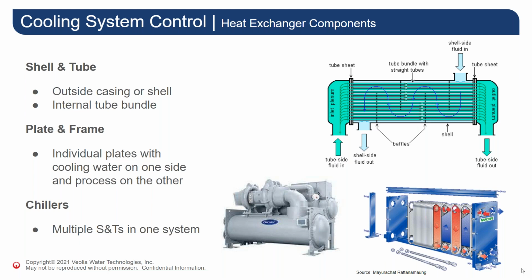Regardless of the type of heat exchanger, they all work similarly. A hotter process fluid, whether it's water, an oil, a chemical, a heat transfer fluid, whatever, a hotter process fluid of some sort passes through the heat exchanger, transferring its heat through a thin metal heat exchange material into the cooling water.